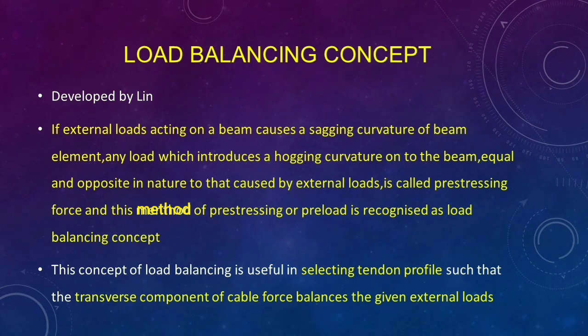In this approach, the external loads are treated only as loads and not converted as stresses on the structure. Prestressing is also converted as equivalent load, and this equivalent load must counteract to balance the external loads. It is possible to select suitable cable profiles in a prestressed concrete member such that the transverse component of the cable force balances the given type of external loads.